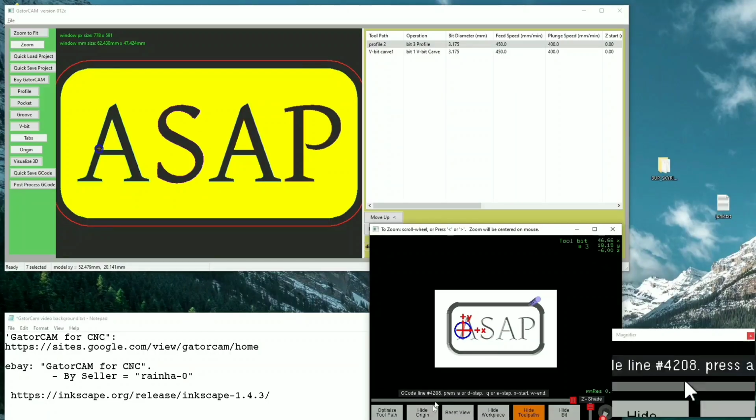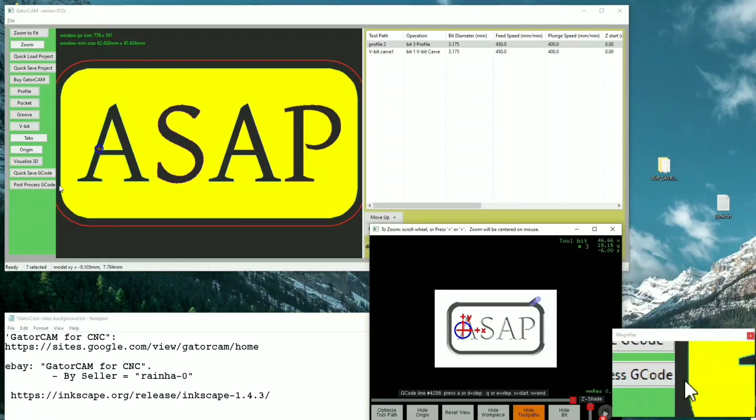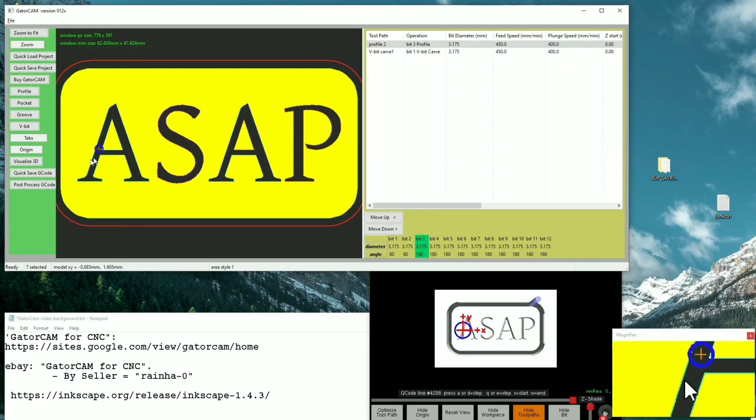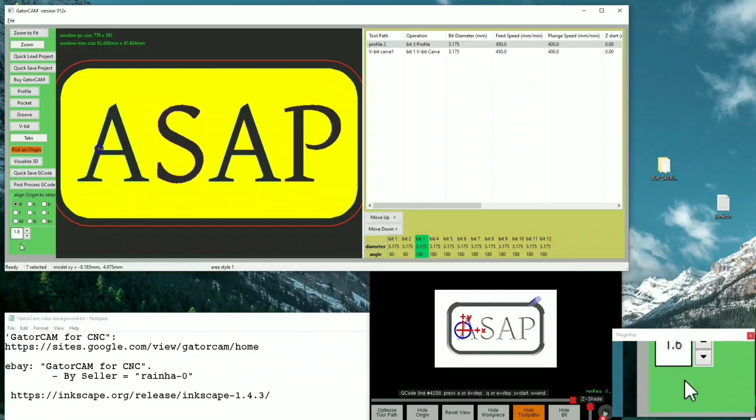Yep, there it is. Okay, so if I put my origin, let's say I want it off the wood, but I want to use all of the wood, up to the edges. So you select an object, like I could select it here, but I want to select the whole object. Go to origin and then click bottom left.